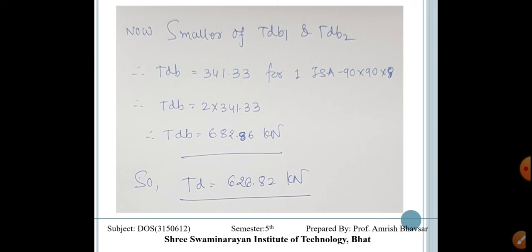So in this case, the calculation to find out the number of bolts is a little bit different, and for the built-up section, whenever we calculate, we multiply that by 2 as there are 2 members in our built-up section. So dear students, whenever we have a built-up section, this kind of calculation must be done by us, and we will get the final design tension capacity of the member.